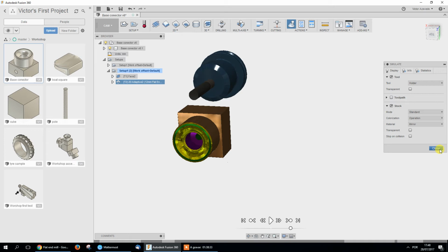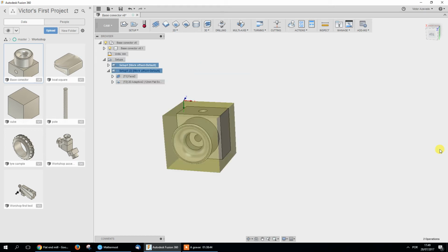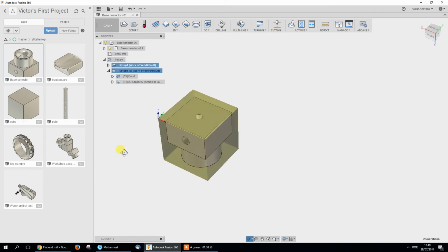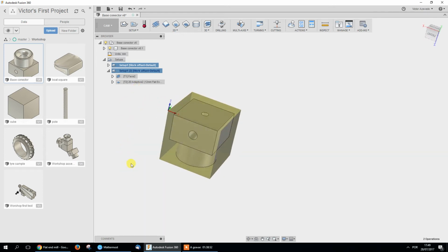Other machine? No, this is all done on the Haas. Always the same machine. You just have to flip the part manually. Yeah, you always have to align the parts. That's the hard part. That's why if it was me, I would start by doing the top part because it's square, and then it's a lot easier to flip, put on the vise, and do the round stuff.